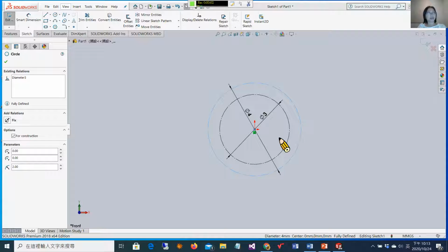In this case, the cam rotates in the clockwise direction. If I want to draw the cam profile, I stay with the cam in the same coordinate system. It means the cam is stationary and the follower has an inverted motion relative to the cam, so the follower rotates in the counterclockwise direction. We need to determine the center position during the follower motion.